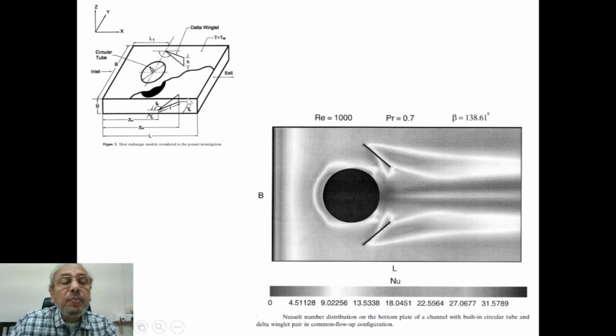So, and bottom plate is also a fin. So these tubes are surrounded by fins, and through the gaps which we can see, cooler streams flow to basically cool the heated fins and the tube through which hot fluid is flowing. This is another fluid. So this flowing fluid, what we are considering now is maybe air, maybe water, a cooling fluid.